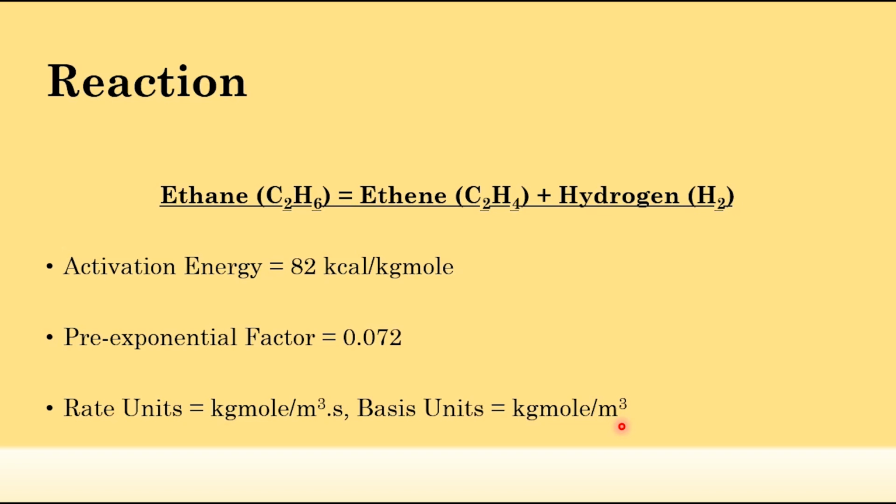And accordingly, once you are going to Aspen Plus, you have to select power law, Langmuir-Hinshelwood-Hougen-Watson equation, or so on, whichever is your requirement. Based on these conditions, we will specify our reaction kinetics, and based on the conditions given in the upcoming slide, we will calculate the conversions, and we will do the simulation in the process and design as well.